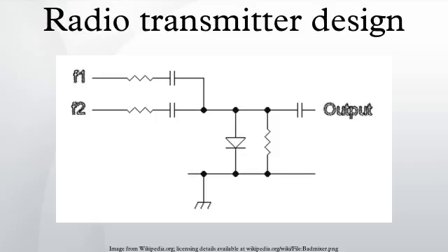Indirect FM. Indirect FM employs a varicap diode to impose a phase shift in a tuned circuit that is fed with a plain carrier. This is termed phase modulation. In some indirect FM solid-state circuits, an RF drive is applied to the base of a transistor. The tank circuit, connected to the collector via a capacitor, contains a pair of varicap diodes. As the voltage applied to the varicaps is changed, the phase shift of the output will change.